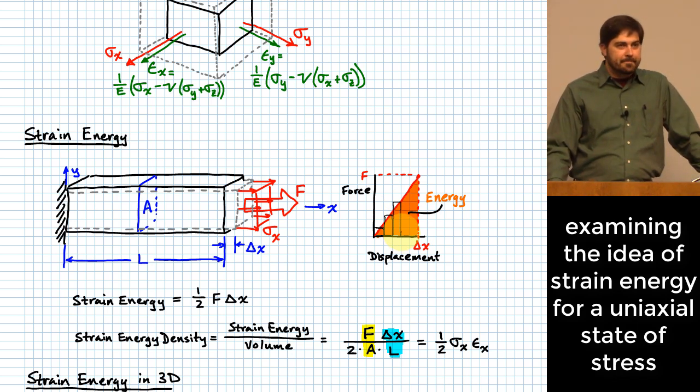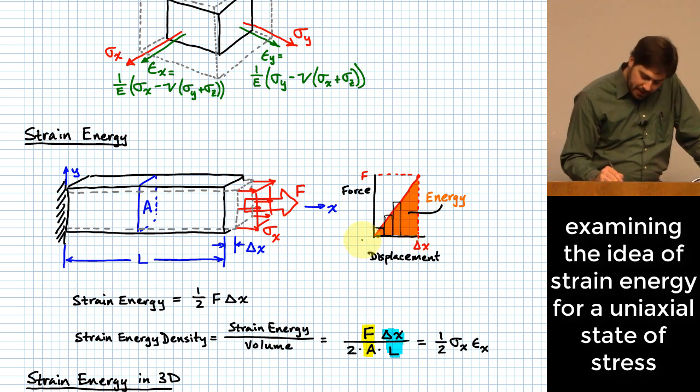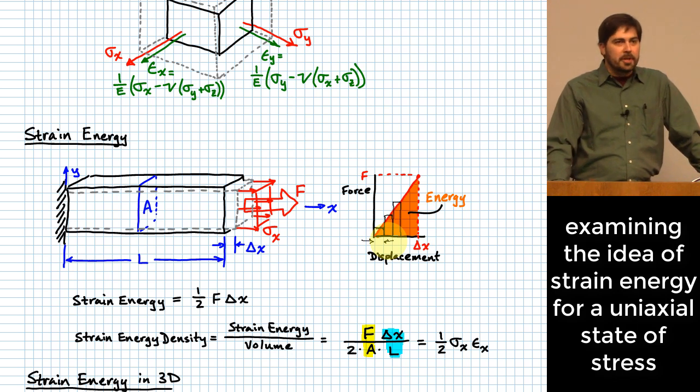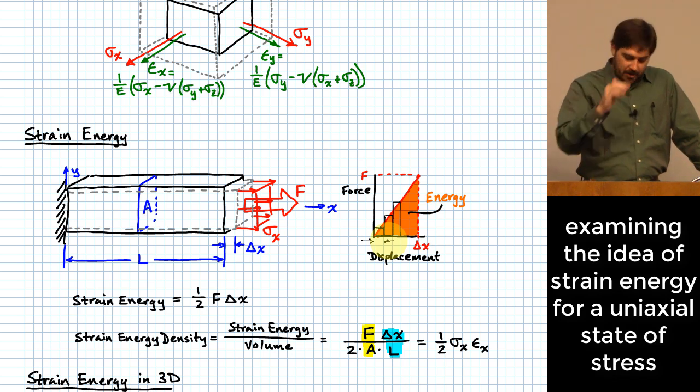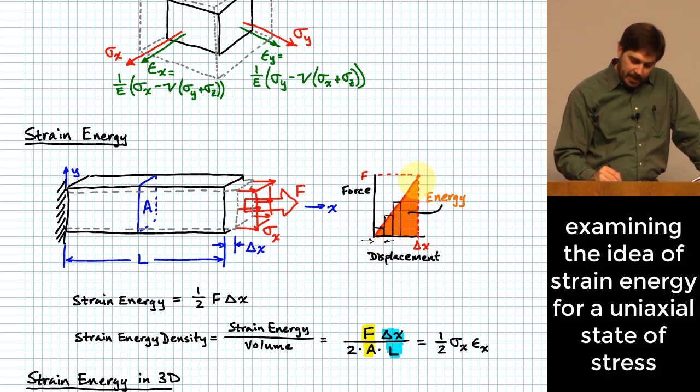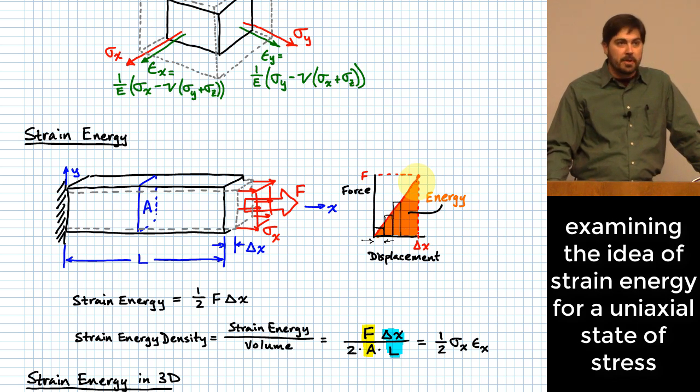See what I'm doing there? Okay? And here's the thing. We don't want to think about putting in finite amounts of energy each time. In order to really make this accurate, what do you have to do? You have to evaluate this for such small steps that they are essentially 0, right? And what you see there is that what we're really doing is evaluating the area under the force displacement curve, and that's the amount of energy that we had to put into the rod in order to get it to stretch. Okay, and this is just the definition of work.